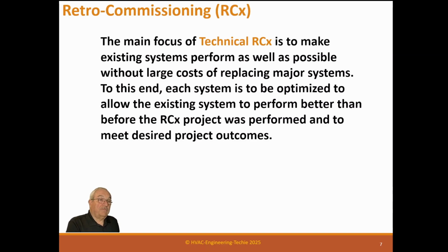The main focus of technical RCx is to make existing systems perform as well as possible without the large cost of replacing major systems. To this end, each system is to be optimized to allow the existing system to perform better than before the RCx project was performed and to meet desired project outcomes. And this is the major difference between retrocommissioning and regular commissioning: when we go into the building, our expectations and the owner's expectations, because he's paying you some money, are that when you leave, the building is working better than when you got there.